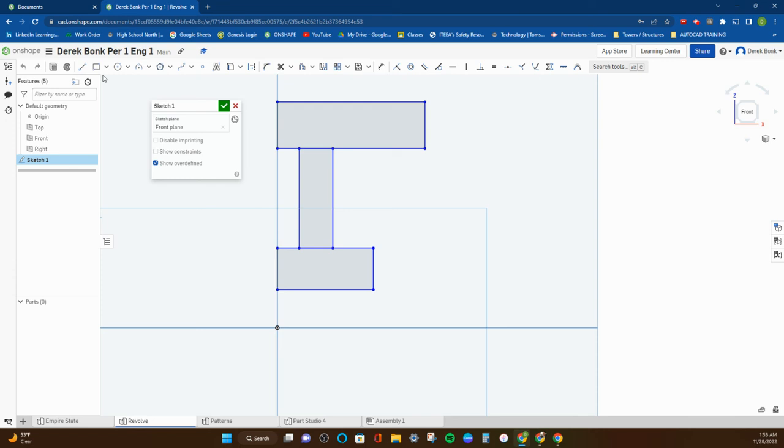And I said the difference between a tool on and a tool off: you'll see a plus symbol for the tool on. If I don't have any tool on, I have this white arrow. You see these could either toggle on, or you hit the escape key on the keyboard to turn it off. I could also right click and hit escape rectangle, which I'm forced to do when I'm using the software that I'm recording with right now. So whenever you see this menu come up and I click escape rectangle, you should just hit escape on the keyboard. But that gives you a white arrow and the ability to modify or drag around anything that you see.